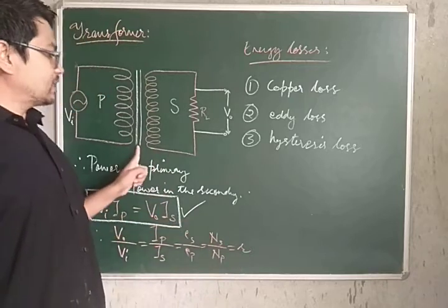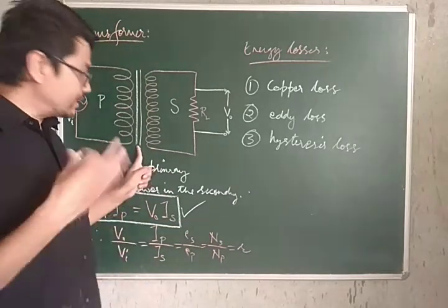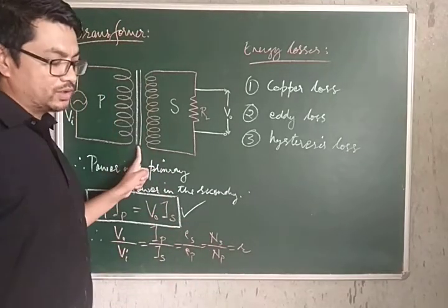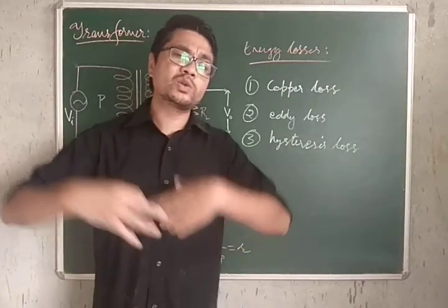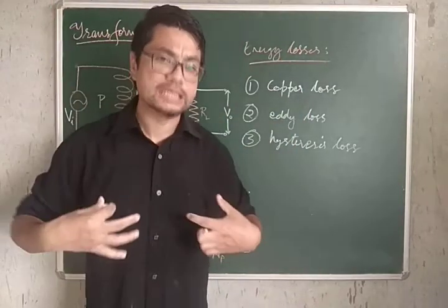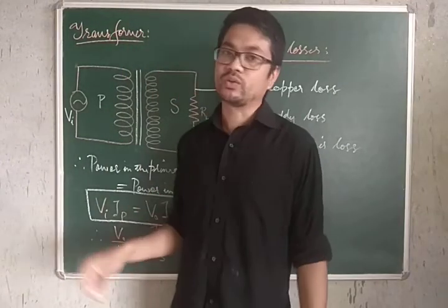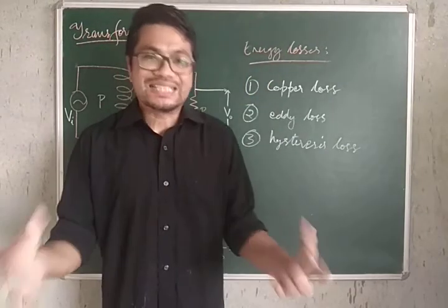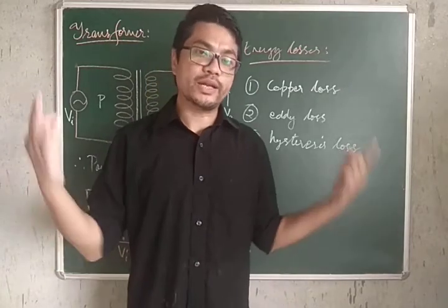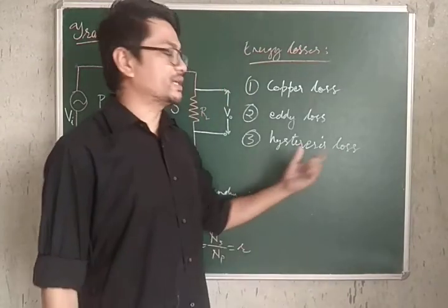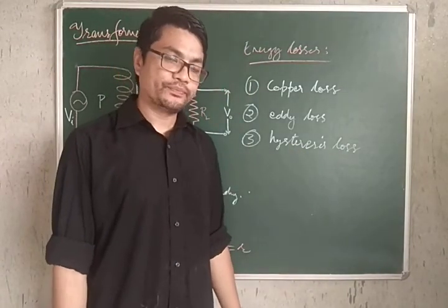So all the while magnetic flux is linked with, or is changed with this soft iron core, this soft iron core goes through a process of magnetization and demagnetization, because of which this soft iron core obviously generates heat energy. And obviously energy is lost in the form of heat, which is called hysteresis loss.